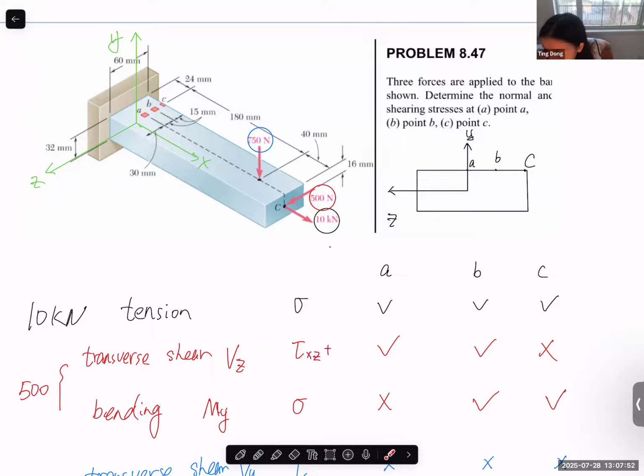So basically, neutral surface is perpendicular to the applied force. Well, you can say it in that way, but I can also say that, do you remember when we taught that in the beam chapter, I just apply a bending moment here directly. I don't apply a force. I apply a couple or a moment. Then how can you say that it's always perpendicular to force? There's no force here, right?